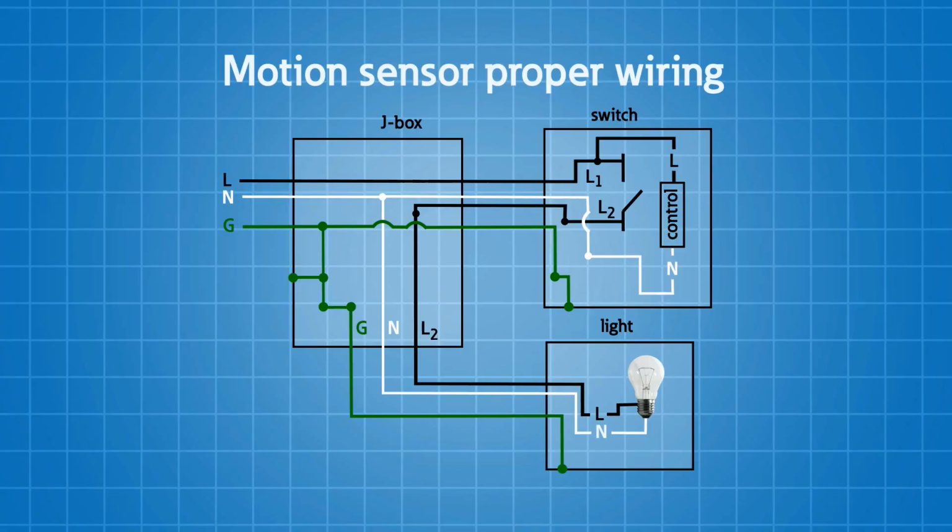So changes have occurred over the last few cycles, 1, to prohibit the use of those products, and 2, to require the pulling of a neutral at those switch locations. So in case you installed a technology that required to be powered up, you're not likely to grab that equipment grounding conductor to get that done. You will properly use the neutral grounded conductor to get that done. So hopefully that helps you understand what we mean by objectionable currents. And remember, all of these terms that we just talked about, it's critical that we use these terms correctly as we communicate to make sure that we all understand each other and we get things right. And hopefully this little review helped you.